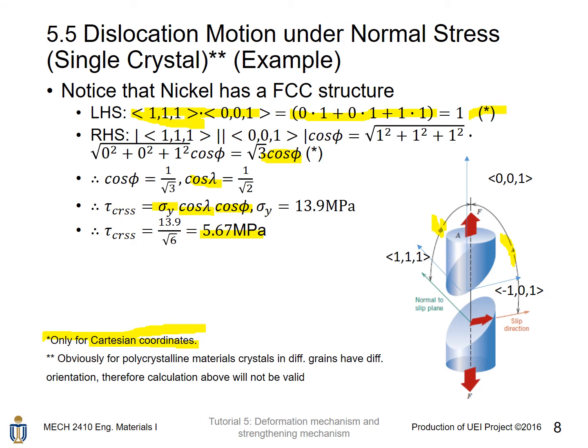And again, I need to re-emphasize it is for single crystals only, as obviously for polycrystalline materials, different crystals within the solid, in different grains, have different orientations, therefore the correlation above will not be valid.